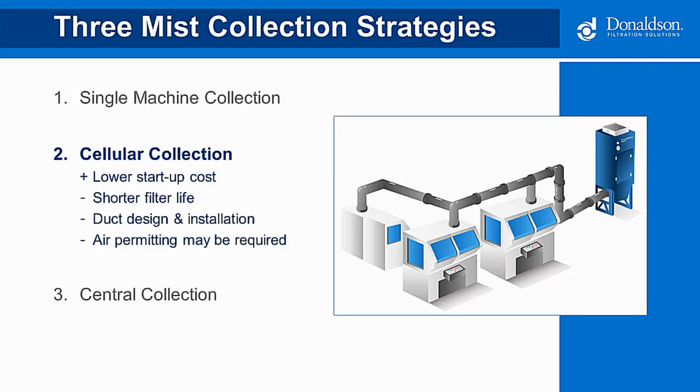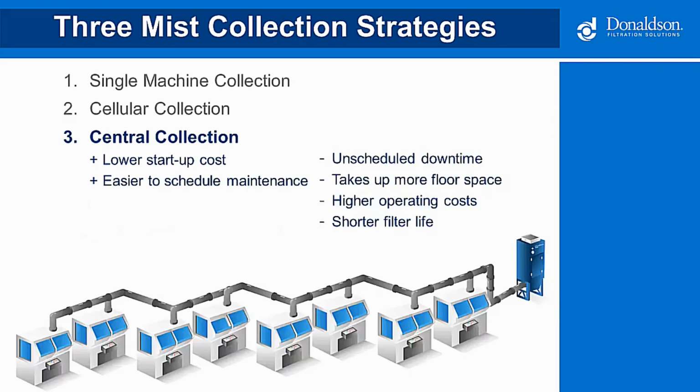And then finally, with larger air volumes, you may be required to get an air permit for the process, even if it's located indoors. You're going to want to consult with your local authority having jurisdiction on permitting requirements in this particular case. So the final strategy would be a centralized system for all machines.